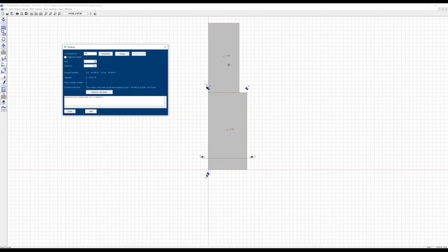So concerning these different depths, we can use here the option adapted to depth. This means that the dewatering is only calculated to a depth which is required at any different point of any section or a part of the foundation pit. And you see, if we calculate adapted to depth, then the capacity is sufficient because our total required capacity is less than it was for a complete lowering by 4 meters.